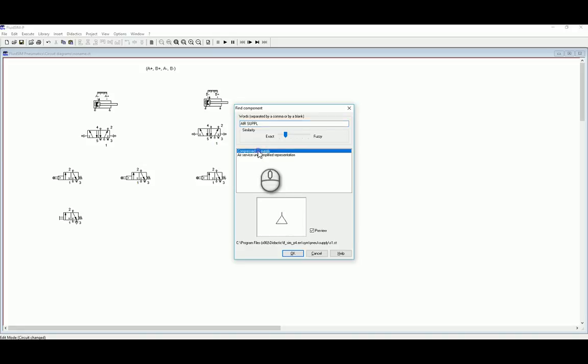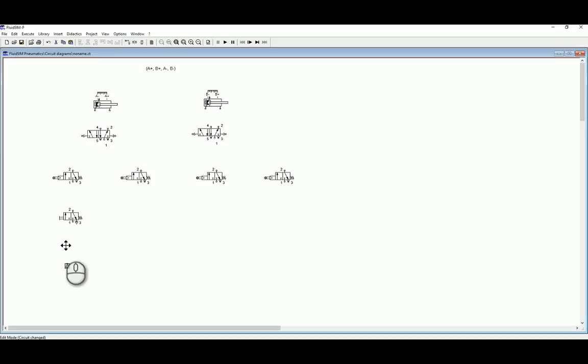One of the last components we should need is an air supply. So we can supply our air to our 3-2 push button valve. Now, in a sequence like this, A plus B plus A minus B minus, whatever component is at the end, so B minus, you need to use that particular sensor in series with whatever starts the sequence to activate the first part of the actual sequence, which in this case is A plus.